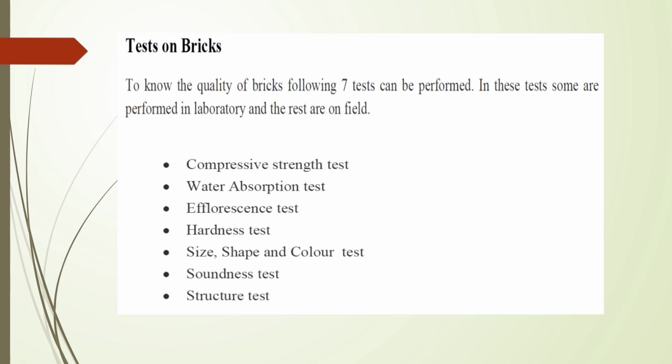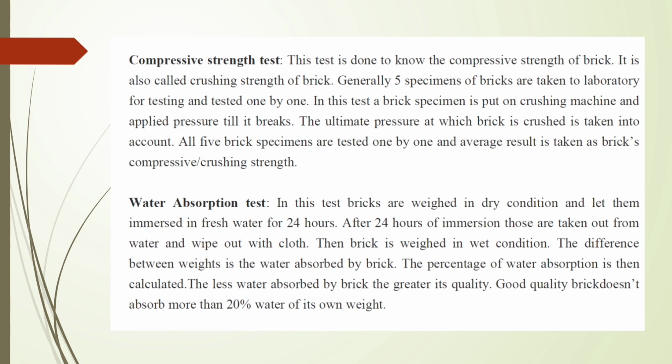Tests on bricks. To know the quality of bricks, following 7 tests can be performed. Some are performed in laboratory and the results are on field. Compressive strength test. This test is done to know the compressive strength of brick. It is also called crushing strength of brick. Generally, 5 specimens of bricks are taken to a laboratory for testing and tested one by one.